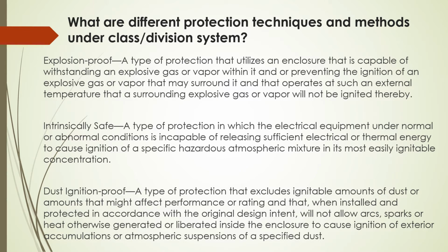Dust ignition proof, a type of protection that excludes ignitable amounts of dust or amounts that might affect performance or rating, and that when installed and protected in accordance with the original design intent will not allow arc, spark or heat otherwise generated or liberated inside the enclosure to cause ignition of exterior accumulations or atmospheric suspension of a specified dust.